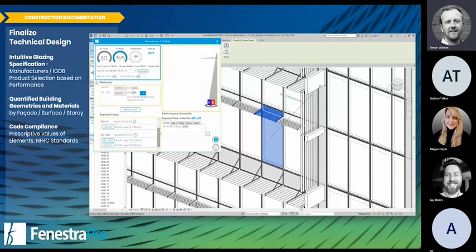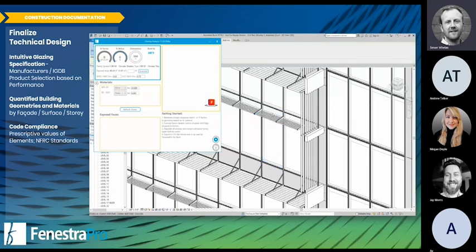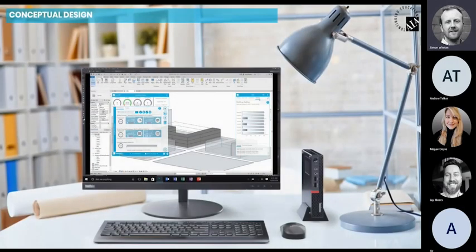And then so if we have a very detailed thermal performance of one panel, we have it for the whole envelope or that whole assembly or whatever that might be. So going back to that kind of my version of the MACC curve, it's early stage, high level decisions, window to wall ratio, outline shading strategies, things like that. Late stage construction documentation, we're into like frame, mullion, spandrel, the thermal performance of your glazing, the edge of frame value, all of that kind of more detailed information.